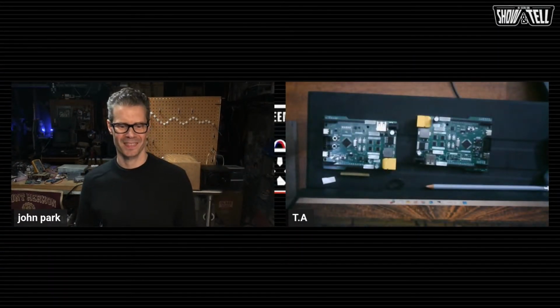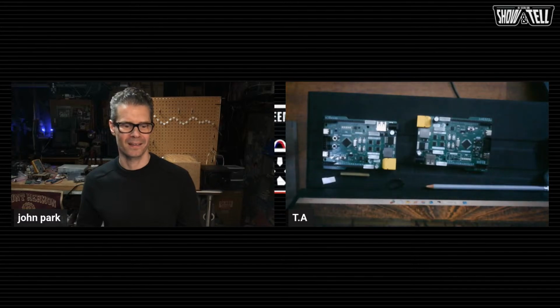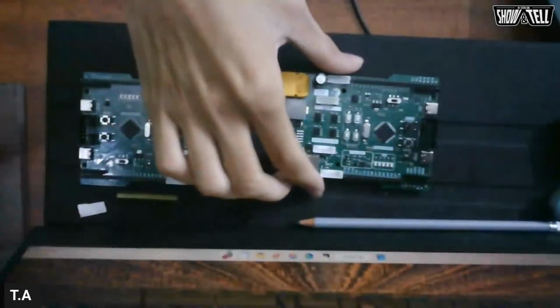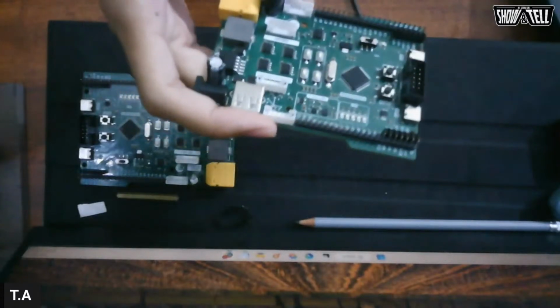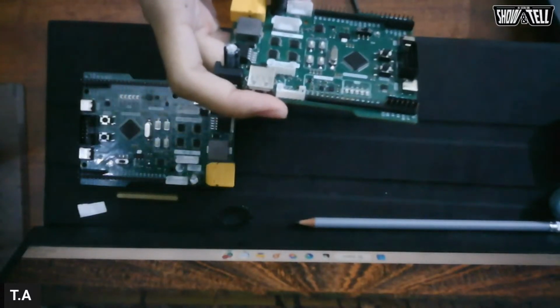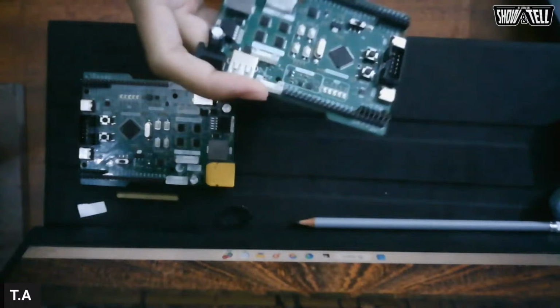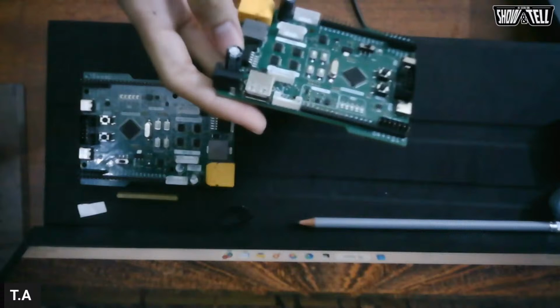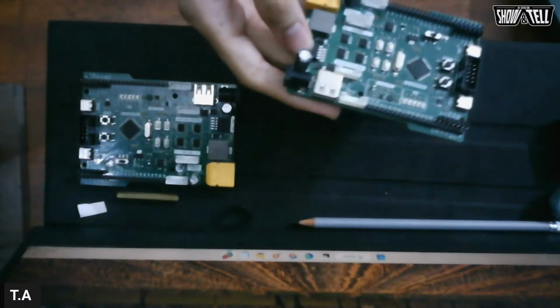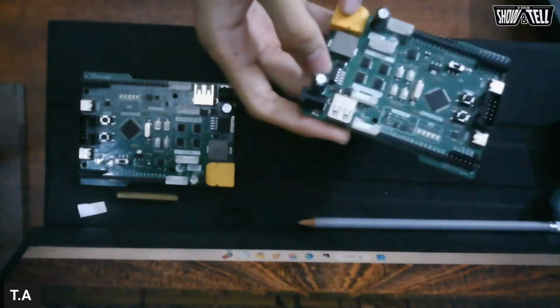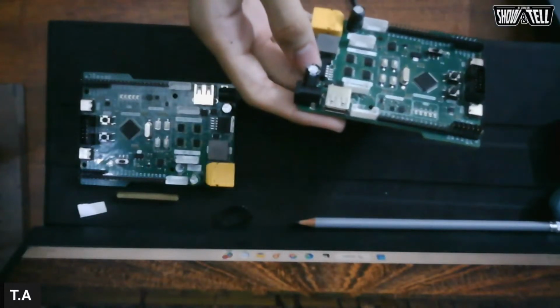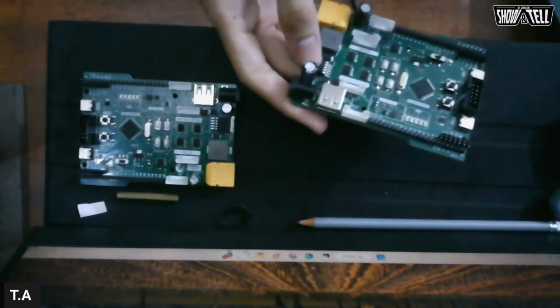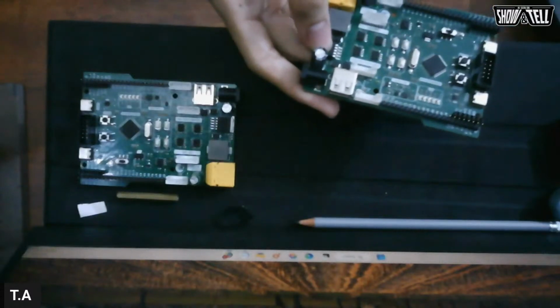Hello. It's morning here in Vietnam, and I just want to show off some of my school projects. I put together a development board for the STM32. The main case is that it can be used as a development board, but it has robotics applications. I've got buck converters here, so you can have the high voltage input power, and then you can have the 5-volt rails. After that, you can have the 3.3 volts that power the microcontrollers.